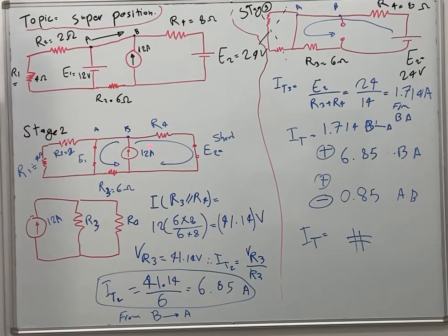So now we've got one source, which is 12 ampere. It goes up, then splits in two. One part of the current will go this way, and the other part of the current will go from B to A, just remember that, and then go back through R3, and then it will merge with the current in the blue line, if you see it, and again it will be 12 from this point to B.